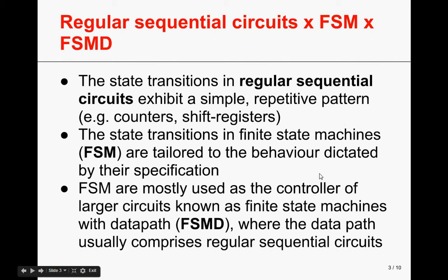Well, to start with, regular sequential circuits have this property of exhibiting a simple and repetitive pattern. Counters and shift registers are examples of regular sequential circuits, and in the case of counters, be it up or down counters, they will simply increment or decrement, so the state transition is indeed a simple and repetitive pattern. And likewise, shift registers will either shift right or left, and again we have a very simple state transition pattern.